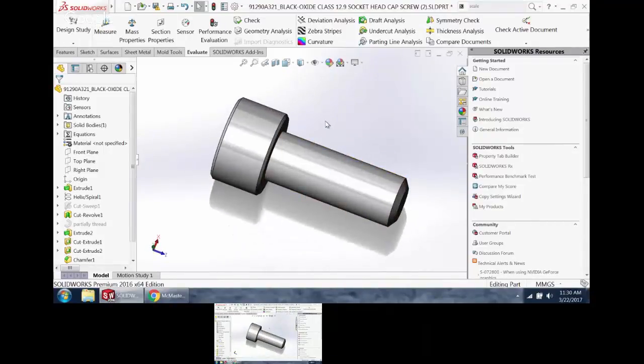If this was brought in as a step file or a parasolid file, you just need to extrude a cylinder over those threads. It'd be the way to do it. But McMaster-Carr is actually a native SolidWorks file, so we can turn the features off if we want.